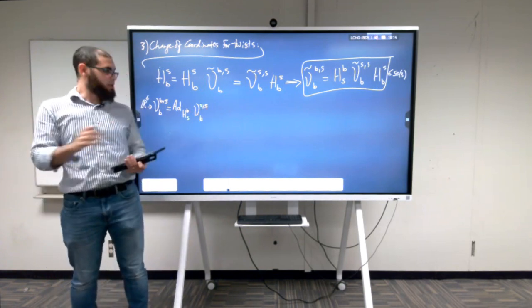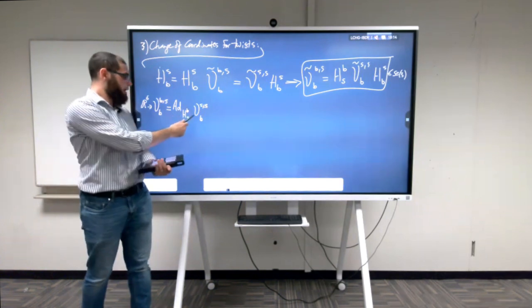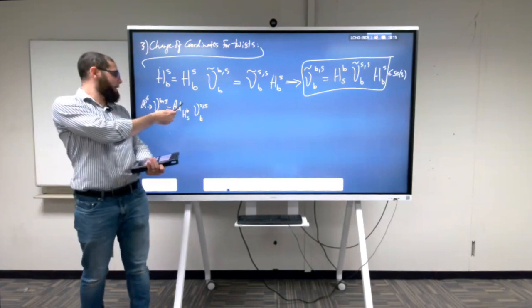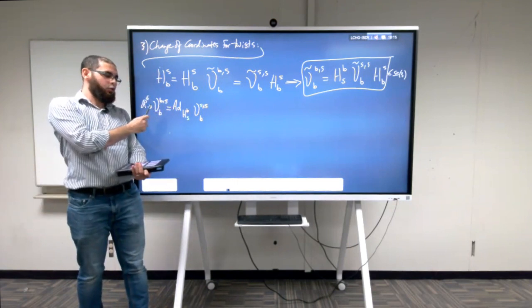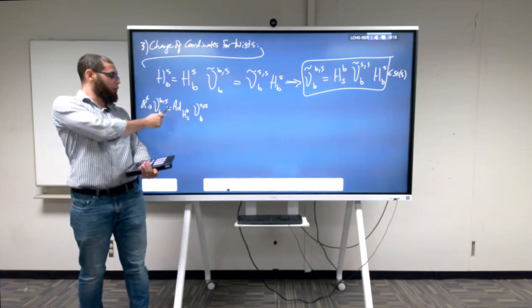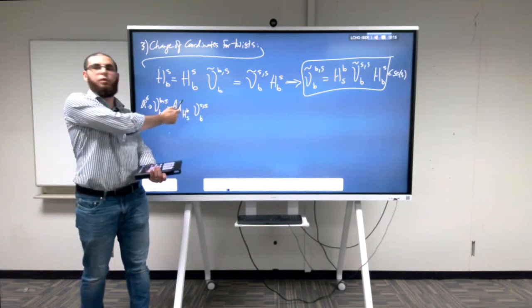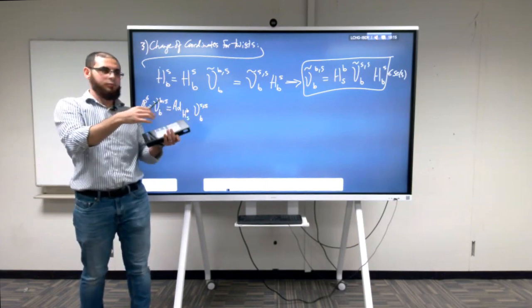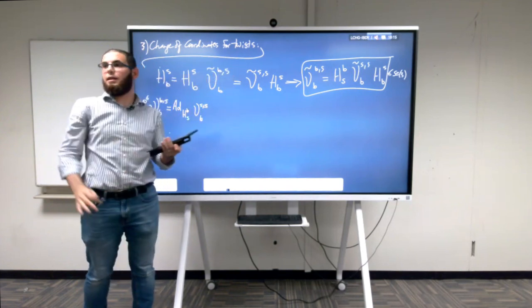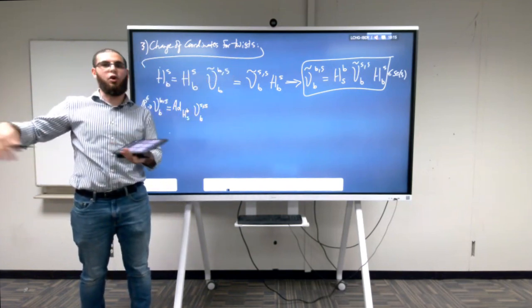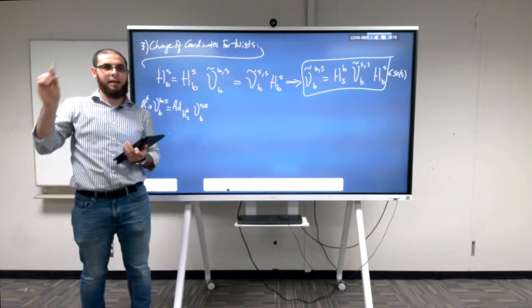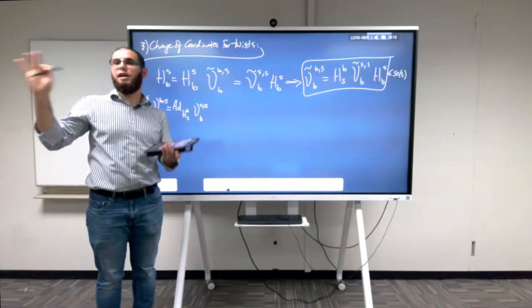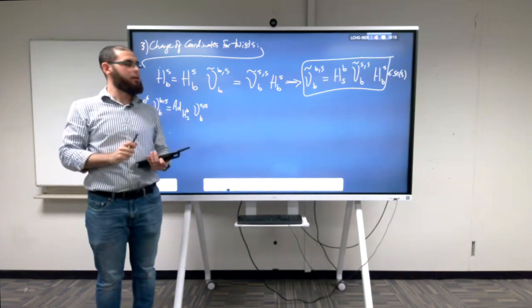This is very important. Because later on, when we have a third frame, so let's say I have the twist of B with respect to S in frame Y, and I want to represent the twist of B with respect to S in frame X, then what do I multiply here? H of Y with respect to X. That's it. So that's why the B and the S here are just because we derived them this way, but you can have a third index. You can always look at twists and angular velocities and velocities from a third frame. And again, this is what I mentioned last time explicitly. Velocities always have 3 indices. So a velocity always has 3 indices.